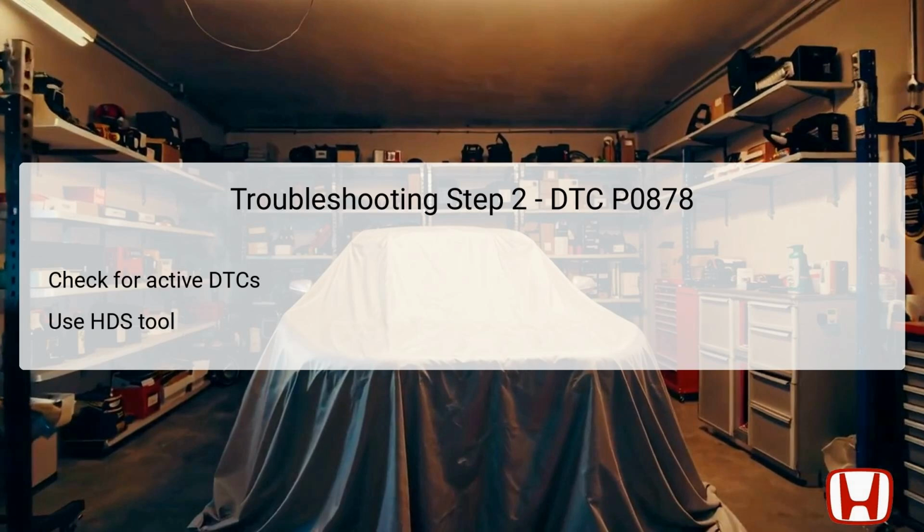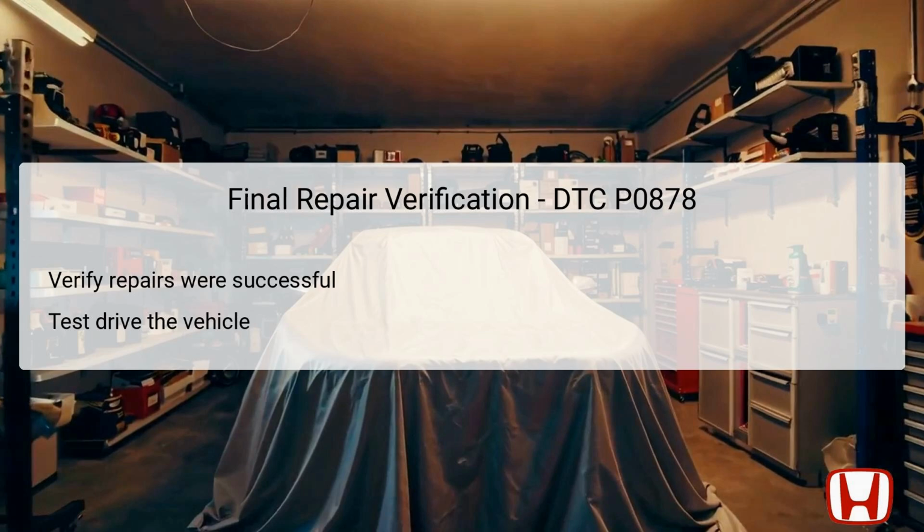After addressing the issues associated with DTC P0878, it is essential to perform a final repair verification to confirm that the repairs have effectively resolved the issue. This verification process begins with a systematic overview of all repairs made, ensuring that any components related to the transmission fluid pressure switch D have been reinstalled and connected correctly.